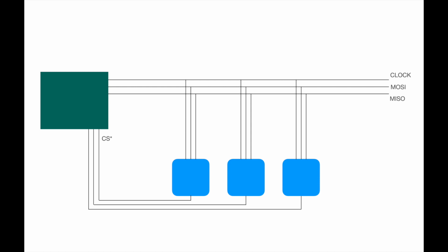The actual transfer of data is controlled by the clock signal, with 1 bit of data transferred in each direction per clock tick. The clock is supplied by the microprocessor, so that's what determines the speed of the transfer. Chip select, as you probably imagine, works pretty much like chip select does on my main board for my various devices. That is, the chip select signals which of potentially multiple SPI devices will be activated for each transfer. So if there's multiple devices connected to clock, MOSI, and MISO as bus signals, the chip select will set any one of the devices connected to the bus at a time to be the target, so that the devices know when they are being addressed.